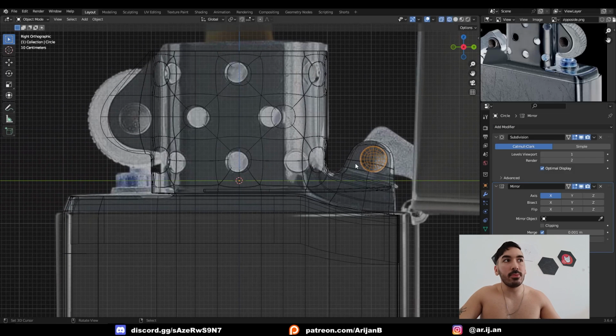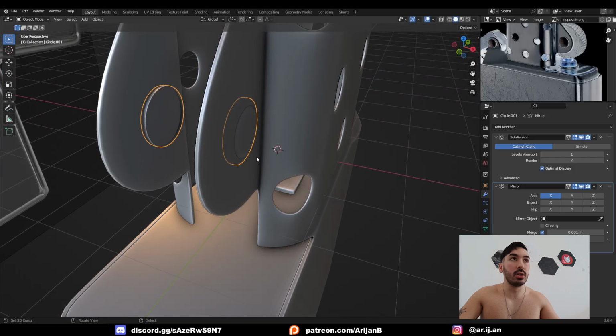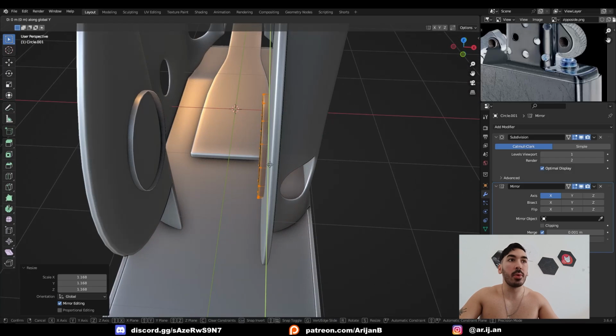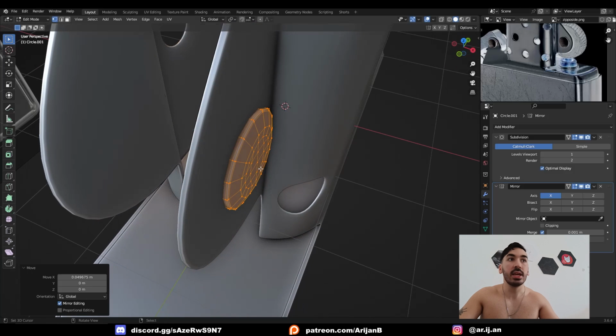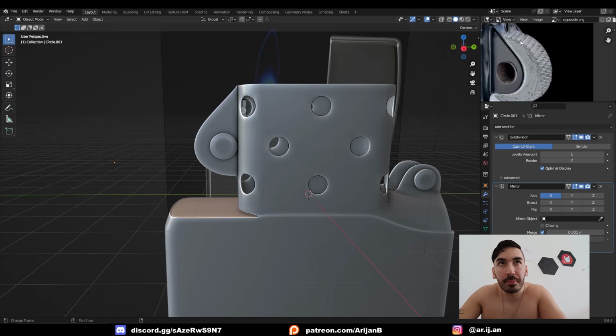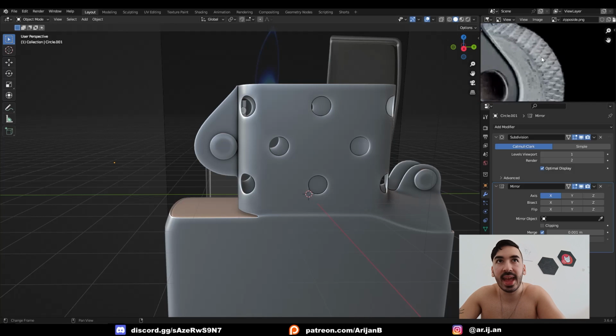We can use this same object in the front here, so I'm just going to duplicate it, but I am going to have to make it a little bit larger. And when you scale it up, make sure that you scale it up in edit mode, because that way your origin is going to stay in the same place. You're not going to mess up the scale or anything like that. I'm going to show you a really cool trick for making this wheel here, because you can see that it has some weird pattern, some weird surface. This would take you about 6 million vertices, so I'll show you a special trick to do that without adding 6 million vertices. But we're going to get to that later.